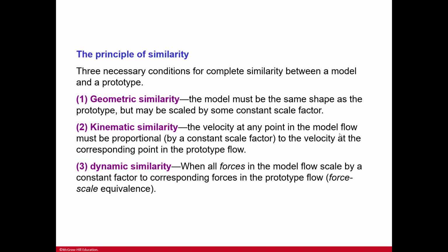Kinematic similarity: the velocity at any point in the model flow should be proportional by a constant scale factor to the velocity at a corresponding point, right? So you want it to be the same as the prototype. You want to have it under the same conditions, under the same environment.